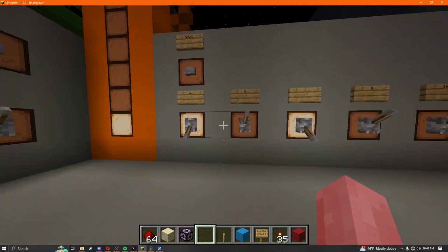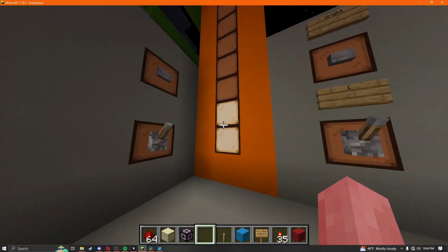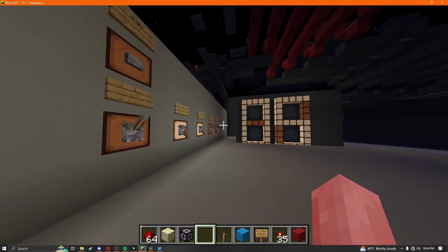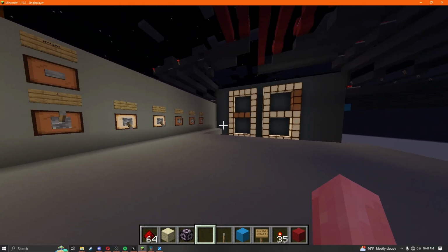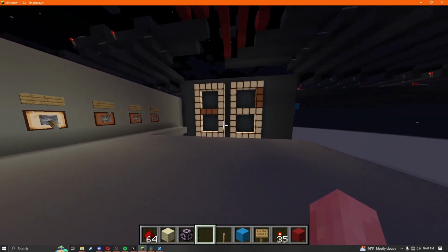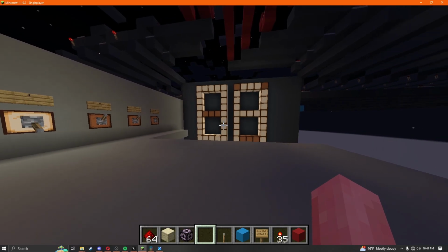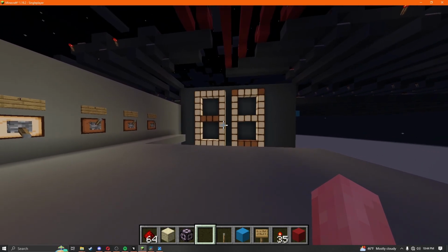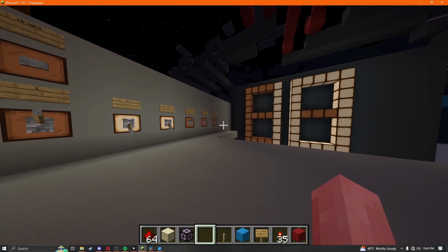Let's add 6. So increment to the next register, add it. I might have been too fast, I might have messed it up, we'll see. So we got 6 in that, looks like it's good. And let's go ahead and add again. So this should roll over to 10 plus 6 is 16 hexadecimal. It's going to be represented by 1, 0. Perfect. So we got 16 stored.